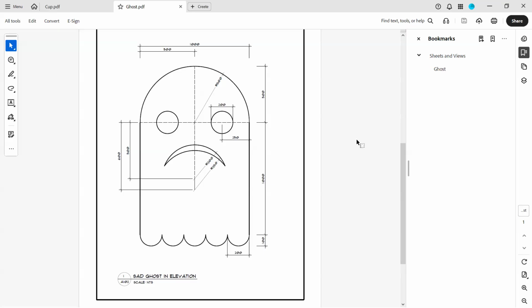Then select this line, and that's 400 away, or 400 down. Up, 400. You click, and it takes. That's offset. Offset and click, very powerful. You need to master that.